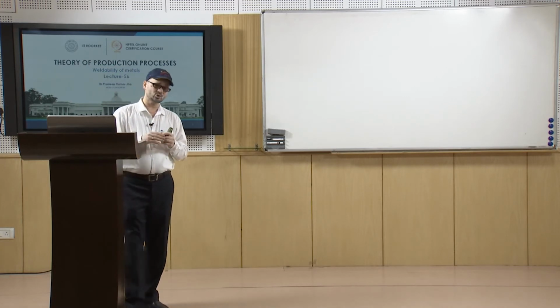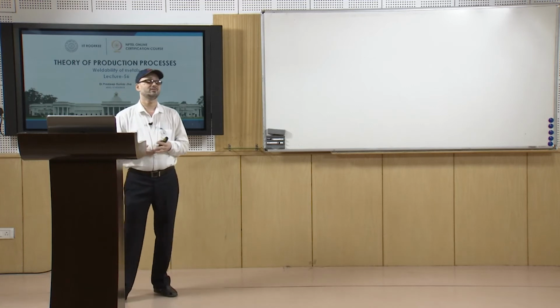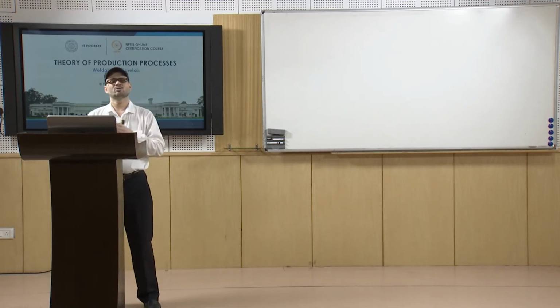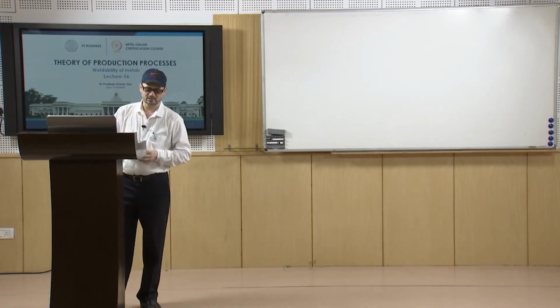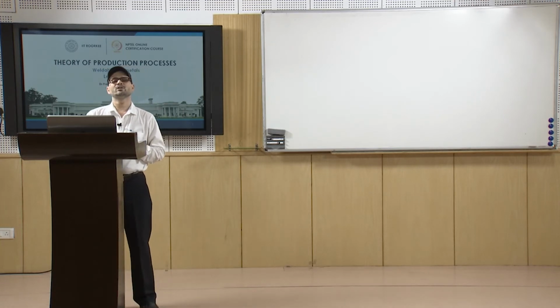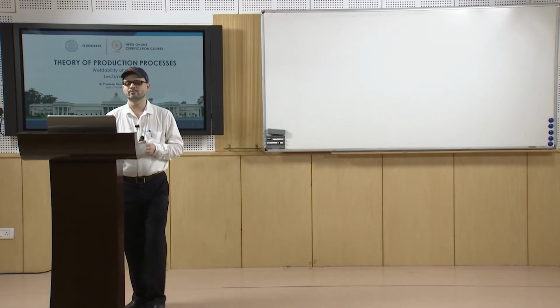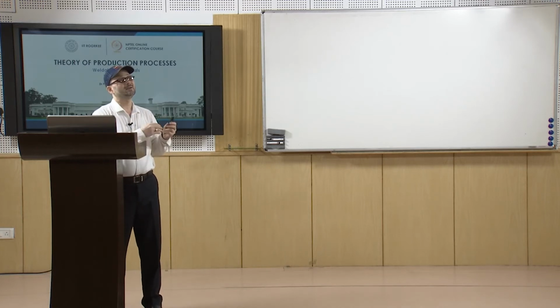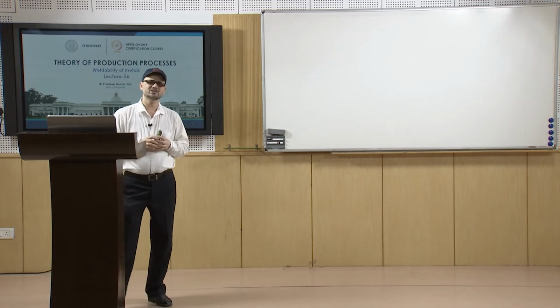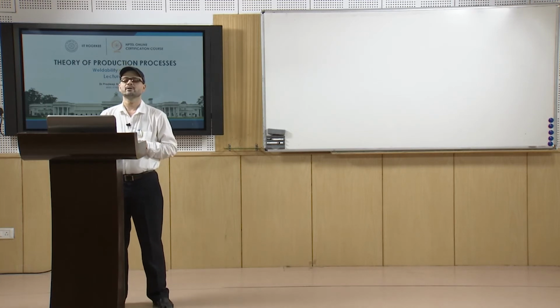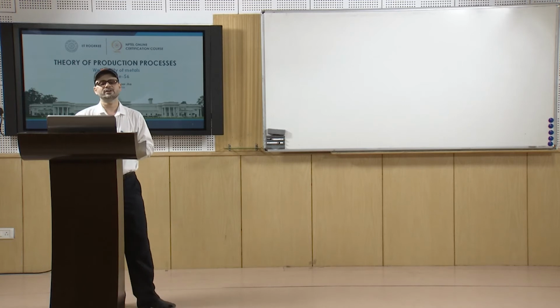Then there is no change in the corrosion resistance of the material after welding, because maybe because of the formation of different phases and undesirable phases at the grain boundaries or depositions, the corrosion resistance may come down. So, that property is also intact, there is no change in that property. Similarly, when you are stress relieving, at that time also there are no brittle type of phases which are formed. So, phase embrittlement should not be there. These are the points which are basically important when we talk about the proper weldability of the material.